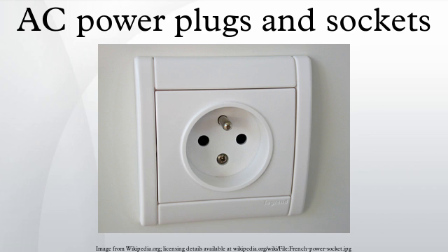The earthed CE 7/5 and CE 7/4 sockets were specifically designed to not allow insertion of an unearthed round plug from older appliances that were earthed via other means, but the CE 7/17 plug has notches to allow it to be used in those sockets by devices not requiring an earth. Round unearthed sockets and plugs are for Class 0 insulation and are not a kind of Europlug. Europlugs are for Class II insulation and designed specifically to plug in CE 7/5 and CE 7/4 sockets.